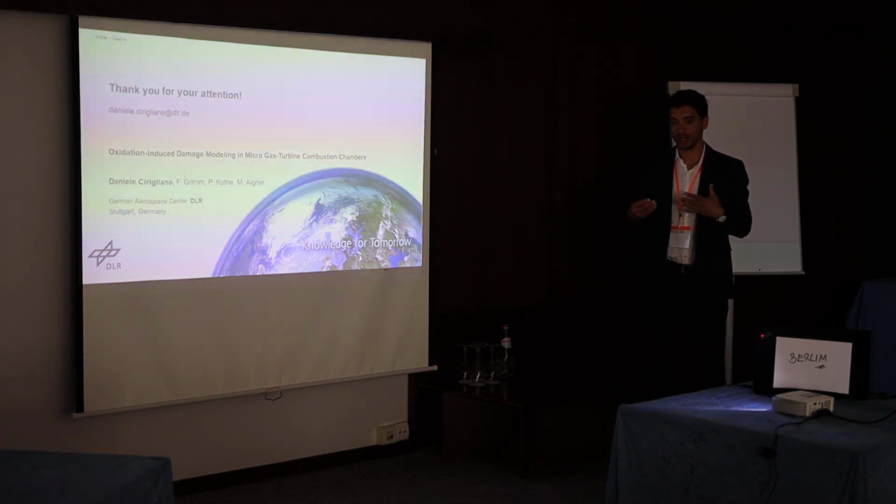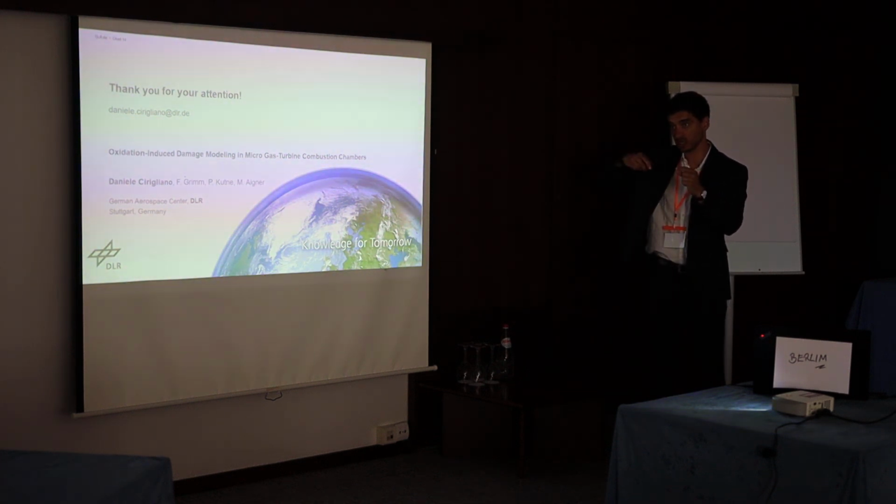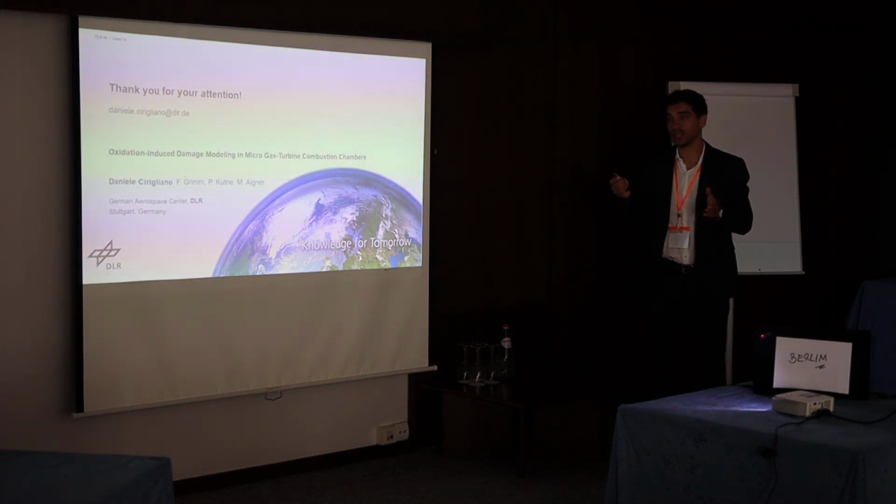So these components are produced in small batches, and also because of the very small size. Due to this very small size, you have fuel inlets with an inner diameter extremely small, in the order of millimeters, and with this very complex shape. To produce those with other techniques, I'm not an expert, but it might be challenging. So I guess that's the reason why those are produced by additive manufacturing.